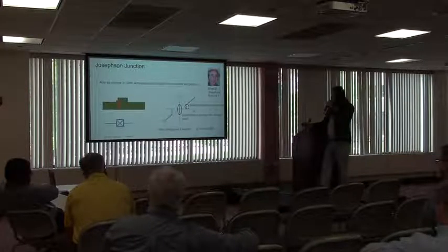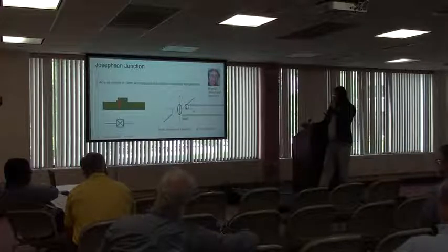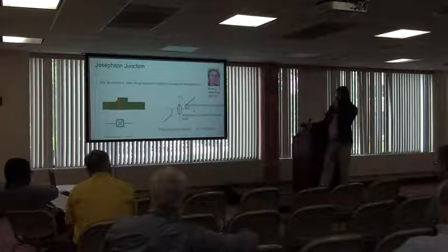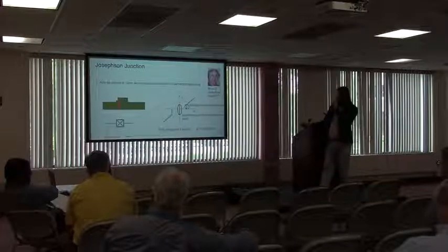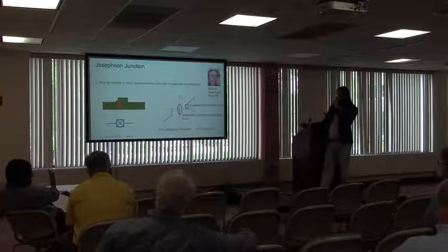The device characteristic is also very interesting. This is an IV plot. Let's say you try to introduce current from one direction to the other. What you are going to notice is that as you introduce more current, you are not building any voltage across the two terminals, between the left and right terminals. It is still showing you 0 volts until you exceed a critical threshold here, and all of a sudden you jump to this point, and you have developed a discrete voltage. And from then on, if you try to increase your current, your voltage is also going to increase linearly.